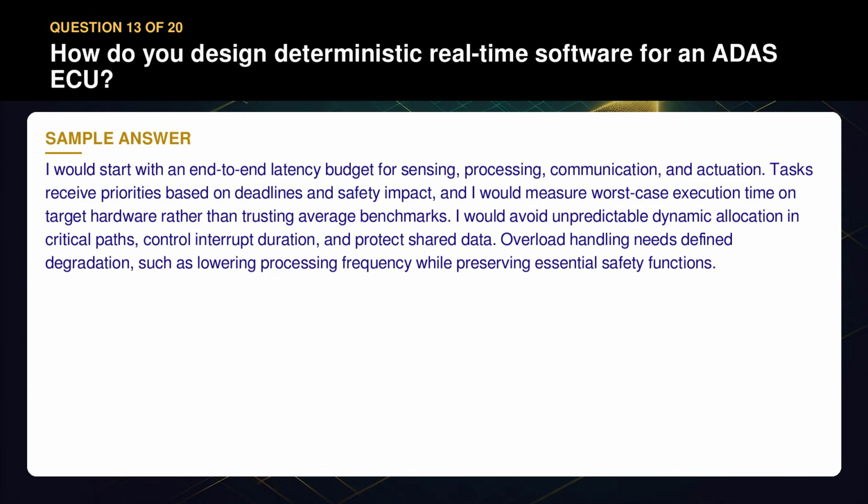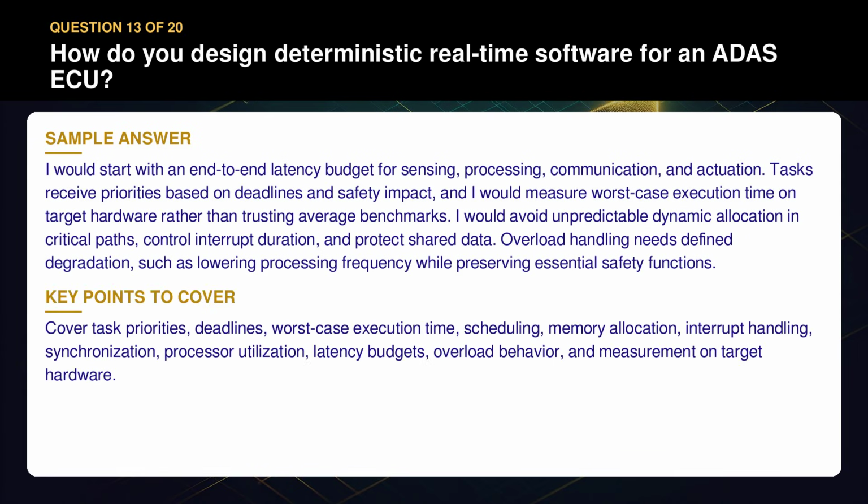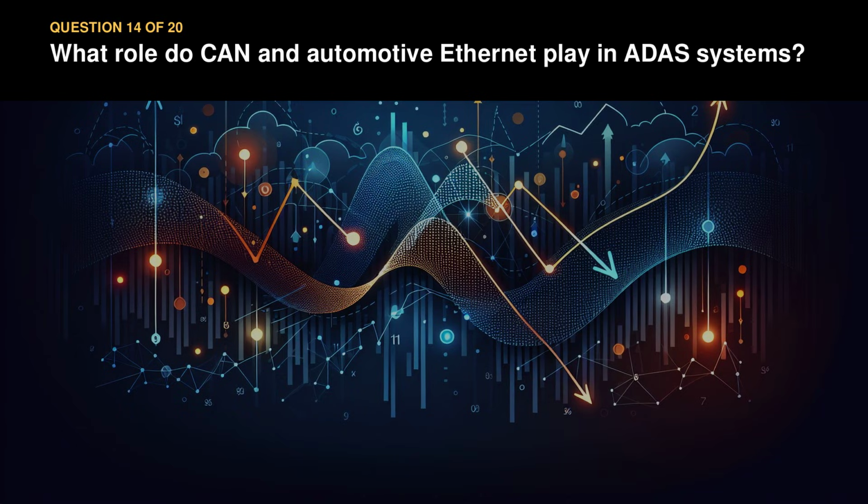Overload handling needs defined degradation, such as lowering processing frequency while preserving essential safety functions. Cover task priorities, deadlines, worst-case execution time, scheduling, memory allocation, interrupt handling, synchronization, processor utilization, latency budgets, overload behavior, and measurement on target hardware.